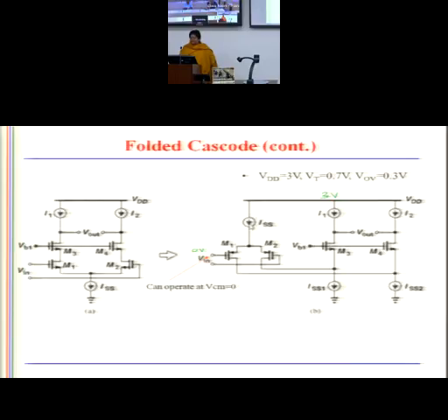Now I replace these symbols by a current mirror. So put a transistor over here, put a transistor over here, and a transistor over here, and a transistor here, and a transistor here. This is your output point. Now look very carefully. Below this point, 1, 2, a stack of 2 transistors. Here also 1 and 2, a stack of 2 transistors.